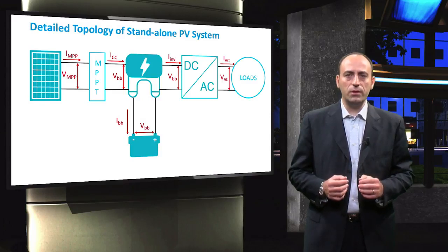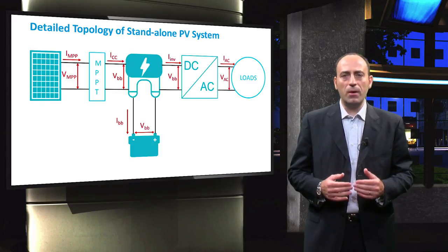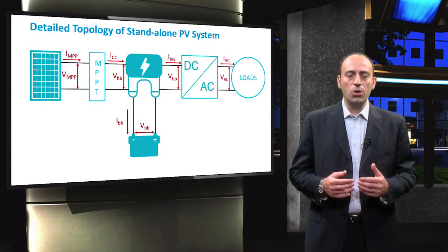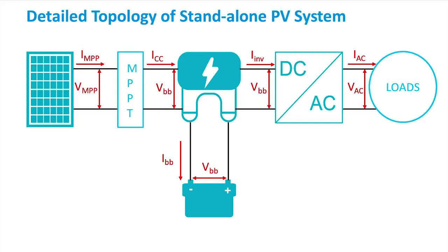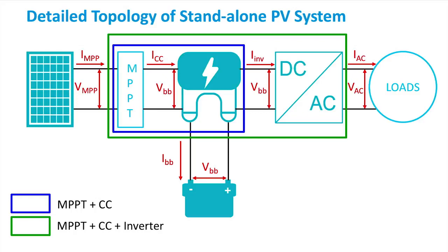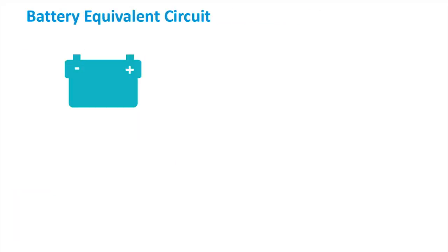Before we proceed further, you have to remember that the maximum power point tracker does not form a separate device in your PV system. Usually, the MPPT is embedded as a power electronic component inside the charge controller. Sometimes, the MPPT, charge controller and inverter are even embedded into a single device. These different parts are linked together inside the device through sub-circuits, each performing its own function. Whatever is the type of device used, the energy flow inside them will be like the topology depicted here.